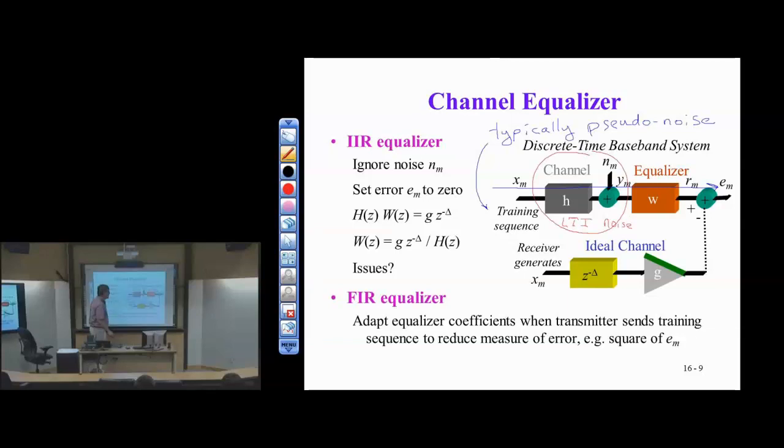And the equalizer's job is, again, going to try to create the right FIR filter to undo the magnitude and phase distortion in the channel. Now, this is not just a communication system application. You can equalize anything. Speakers, microphones, biomedical test equipment, it doesn't matter. As long as you have the ability to send some known calibration signal and then adapt or train an equalizer to compensate for whatever the impairments are, this is an incredibly effective method. And this method we'll do today works in any application. It's not specific to communication systems.